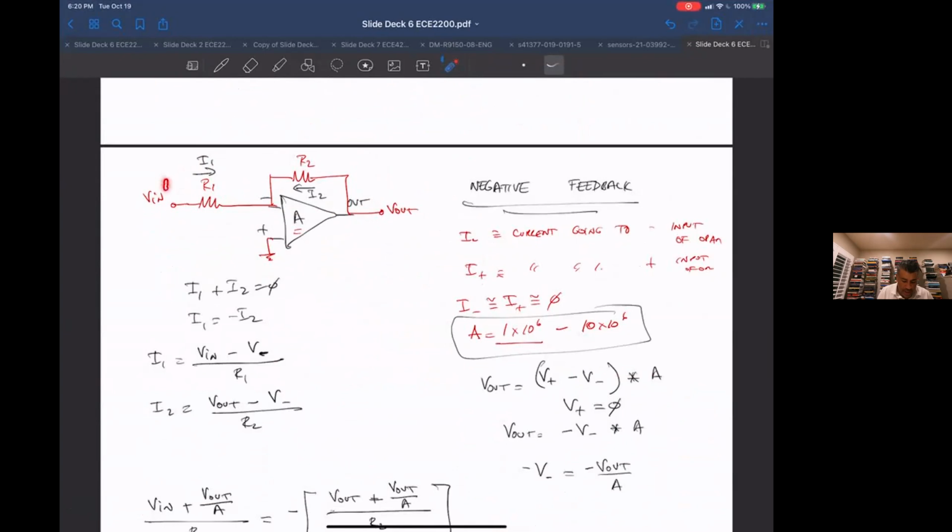If you get a change in voltage here, you get a 10x change here because of this feedback, but this minus node is always going to be more or less around ground. No matter what this input does, this feedback makes sure that this node comes back to the same value. Just how it works. Again, you've got to get some experience with feedback to get that.